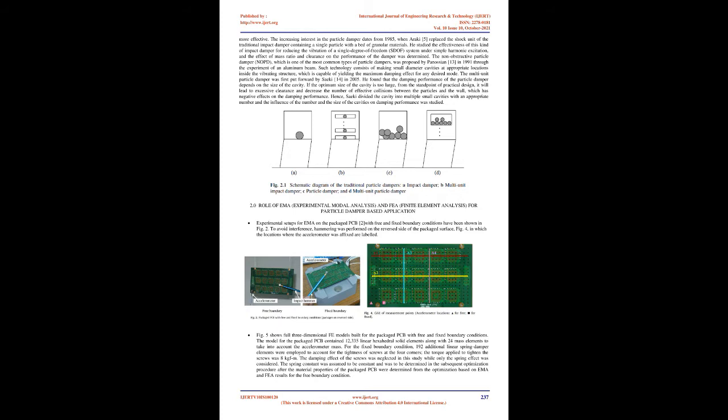The increasing interest in the particle damper dates from 1985, when Ibrahim [5] replaced the shock unit of the traditional impact damper containing a single particle with a bed of granular materials. He studied the effectiveness of this kind of impact damper for reducing the vibration of a single degree of freedom, SDOF, system under simple harmonic excitation, and the effect of mass ratio and clearance on the performance of the damper was determined.